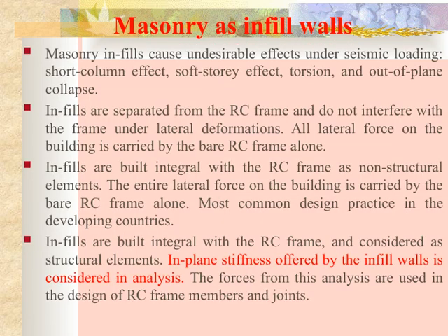Let's talk about masonry as infill walls and how they behave under seismic loading. Infill walls made of masonry can cause some undesirable effects during earthquakes, such as the short column effect, the soft story effect, torsion, and even out-of-plane collapse. These issues can significantly impact the building's stability and safety.